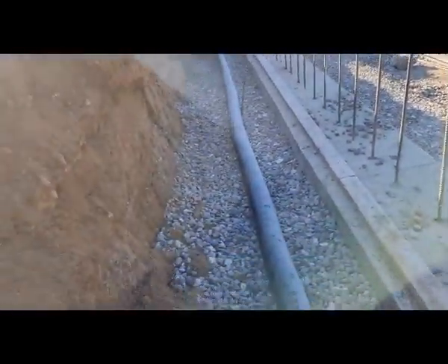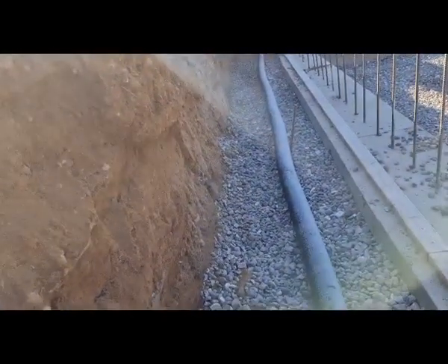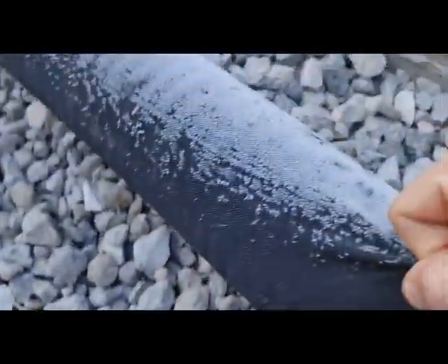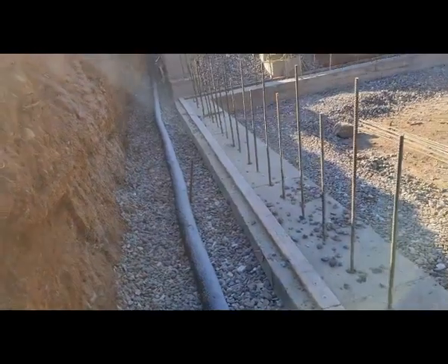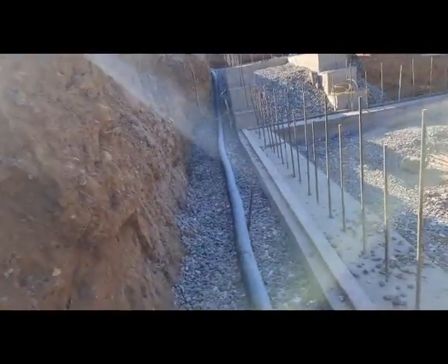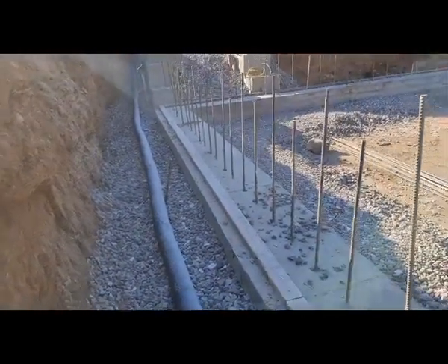Now, under it, I use perforated pipe with a black sleeve, this filter fabric. So these pipes I use already come with a filter fabric. Otherwise you can use other pipe, but it's a little bit more expensive. The other black pipe doesn't have any filter fabric, so you have to put filter fabric on it. So I like to use those pipes.